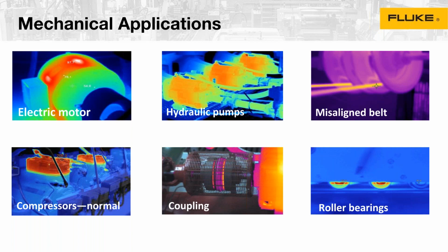And again, when you think of infrared, it's not only about troubleshooting. It's also about doing a baseline or commissioning. There's a lot to be said for knowing what good looks like from the get-go. This way you have something to refer to when you start having an issue, or when you start a proactive maintenance program, where on a regular basis you say, 3 months ago I took this picture of this hydraulic pump, and now 3 months later it has increased by 25 degrees, in the exact same spot. Is there something in the process or in that piece of equipment that really changed? It shows why it should have increased 25 degrees.